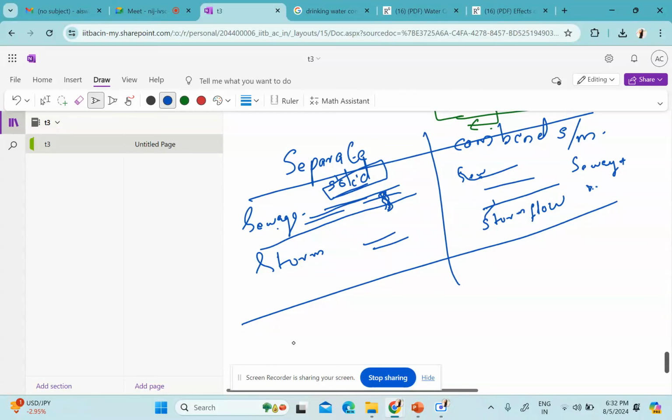In a combined system, due to the storm water flow from the upper surface itself, a lot of solid contaminants can flow through the drainage pipe, and there is a higher possibility that it will clog the way. Also, when a lot of water is flowing, a lot of pressure can be felt on the outer side of the pipe, and this pressure can initiate cracking.